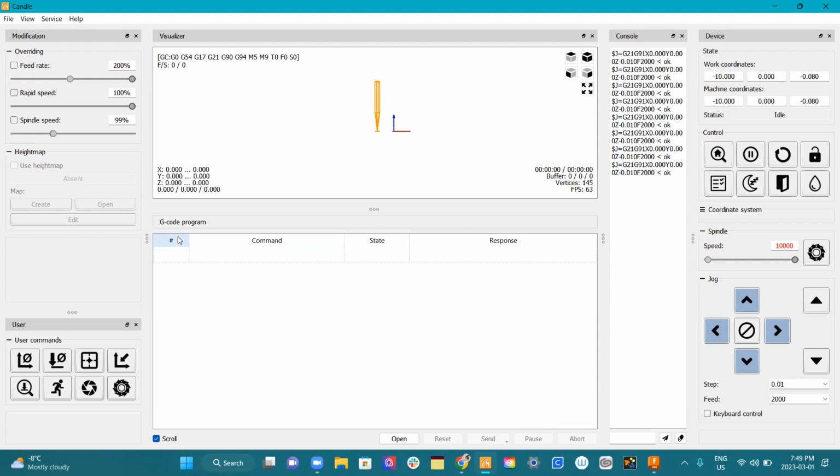Yeah, the problem is if the metal is bent, when you adhere it, it's an adhesive thin sheet. You put it on the thing there, but it can be bumped up because tinfoil creases. And then if it touches the crease, it's not actually going to figure out the real true height of it. Also, it has a thickness, and so you're going to have to offset by the thickness of tinfoil when you do the programming for it. So this is all if you just want to have a sort of shallow cut. If you're being precise. Yeah, so if you have wood, you're going a half inch into the wood. Who cares? Yeah, if it's not too uneven.